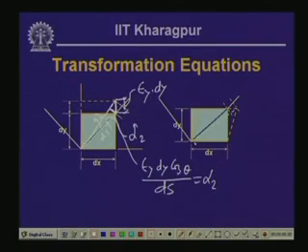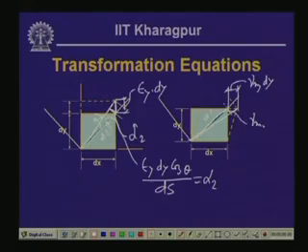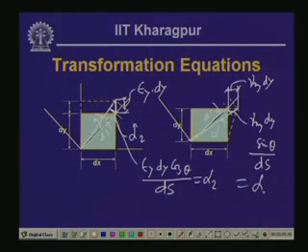Similarly, when we had the shearing strain, the diagonal was original length of ds, finally it has taken the form which is here, and the extension of this particular length in terms of the shearing strain is gamma xy dy, and again since this angle is theta, this particular value is gamma xy dy sin theta, and that divided by ds will give us the angle alpha 3, which is again in the clockwise direction. So, this is equals to alpha 3.